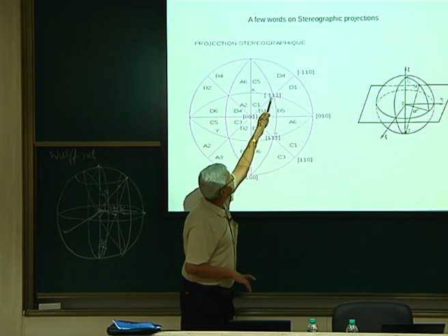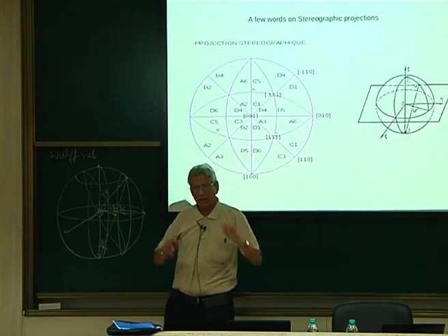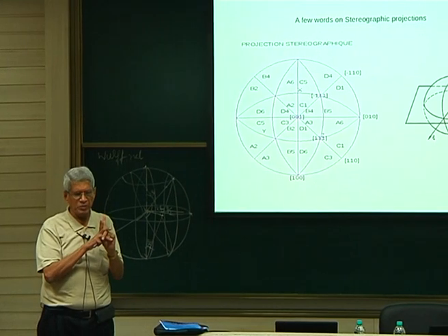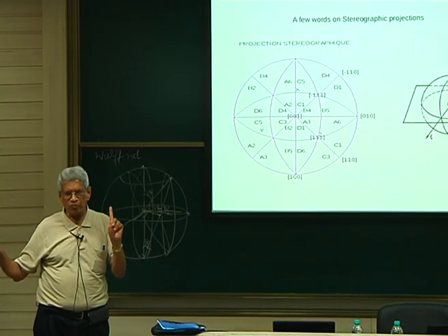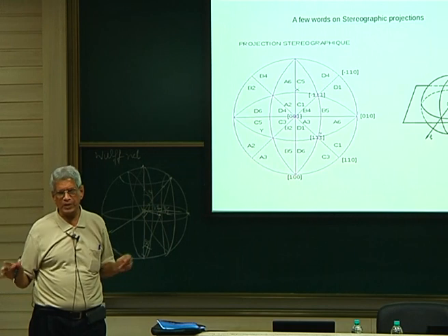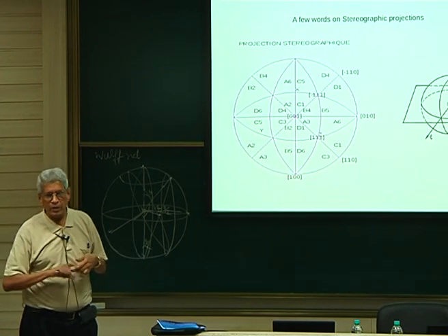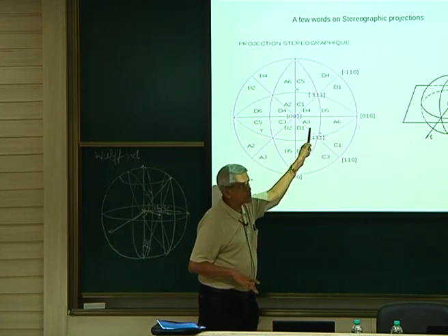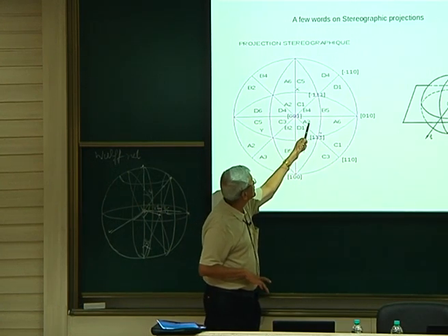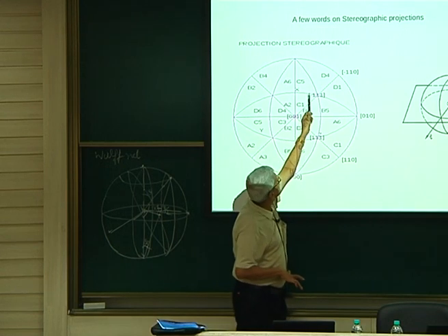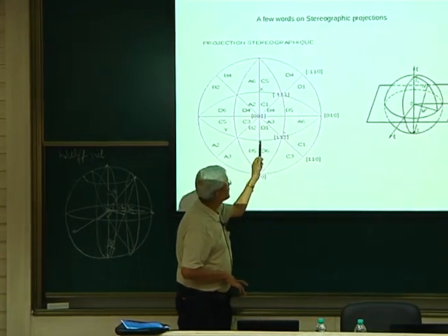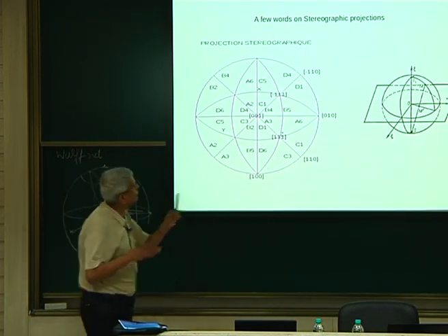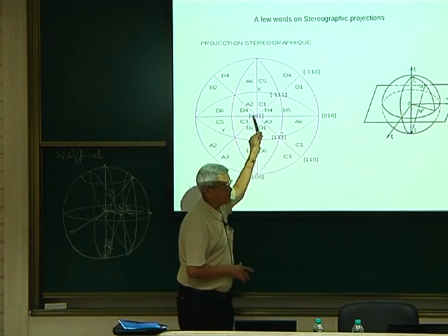With respect to that, for this plane, the angle with respect to the plane may be very small, but the Burgers vector angle will be more. Finally, when you take the product, the Schmidt factor will turn out to be small. So this way, we can identify the slip plane. If I choose any beam direction here, I can tell that this is the slip plane and this is the Burgers vector. That means this defines the slip system. Only this slip system will be active in this area.